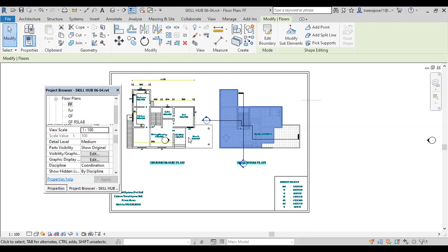Normally, everybody aligns it at the first floor level, makes the model, then moves it onto the model created in the ground floor. That is not the better way. You align the AutoCAD image into the corresponding proper position, then do the work. That is the procedure that we are doing.